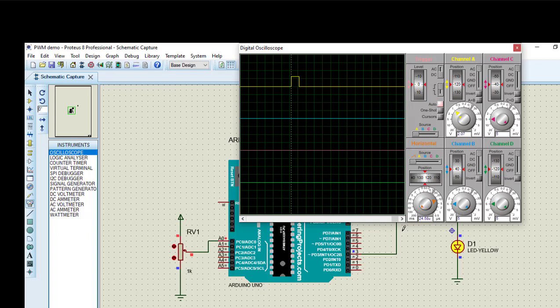It's especially in the way it's implemented in Arduino. In the Atmega, it would be a bit more complex. You remember that we have to set up the COM bits. We have to set up what type of PWM we are doing. Are we doing fast PWM, or the other types of PWM? And then we have to go to great pains to look at the TCCRs, and we have to look at how we set the clock bits and all of that.